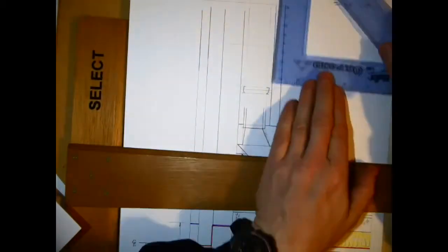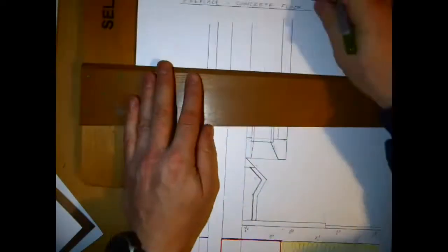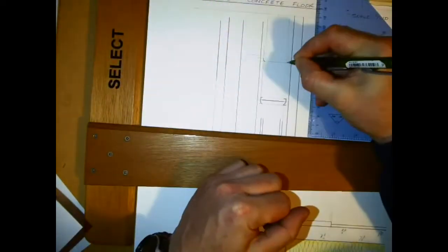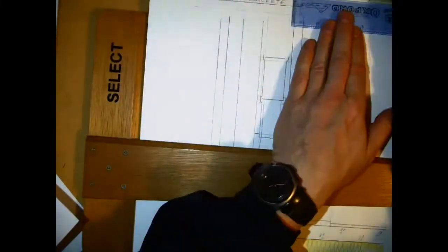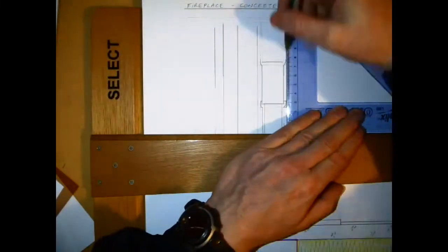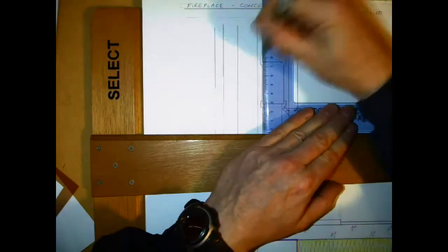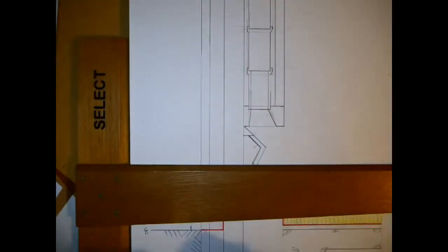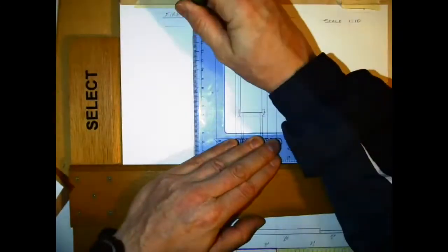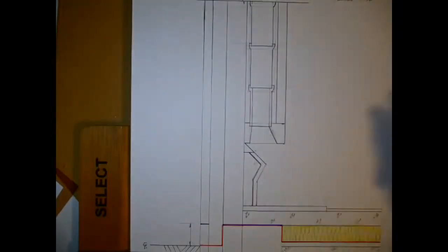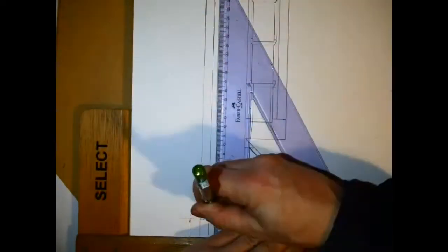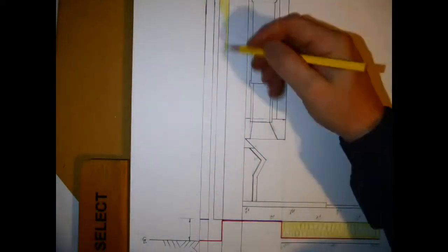They will give you a minimum size of 194 for a flue gathering, but in this here I've made it 240 millimeters, so that's the size that I have here, and I've taken roughly 30 millimeters in either direction of the center line of the flues, which are 460 millimeters in height, to draw the spigot. It's the general shape that you need to get right. The specifics will not be that important, but the general shape will.